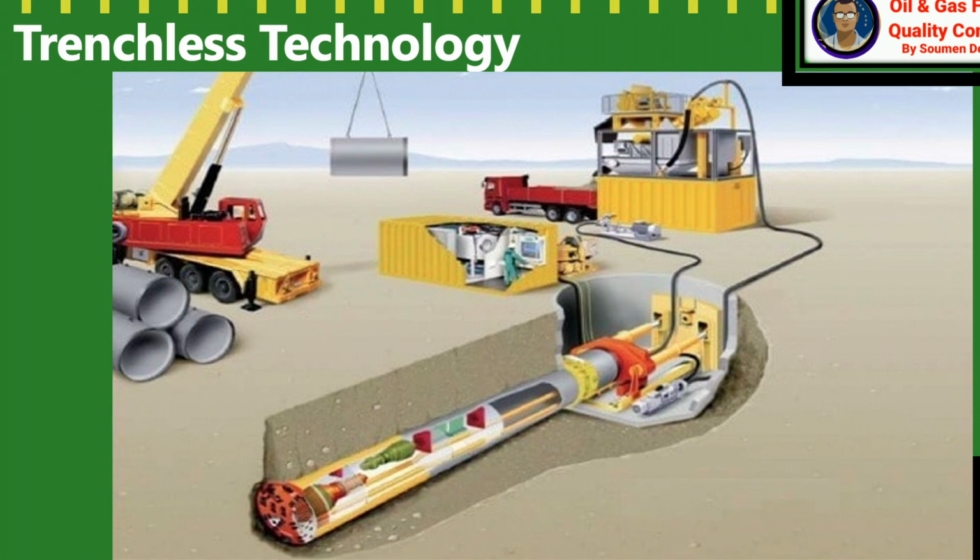So, what are trenchless construction methods? Trenchless construction consists of installing pipes, for example culverts and utility lines, via tunneling under a highway. It should be considered in areas where conventional open trench construction methods are undesirable. For example, we have a highway or a railroad where we cannot stop or reroute the main road and the traffic flow should not be impacted. In that case, we use the trenchless construction method.